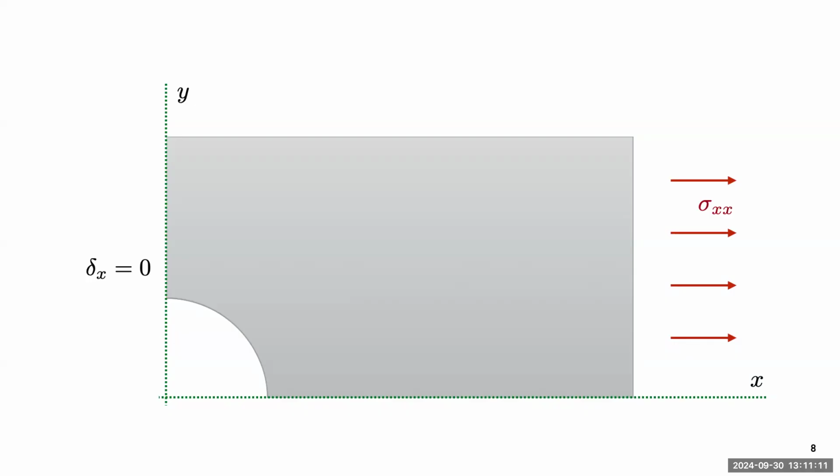And so then the normal direction to this symmetry plane, how do you find the normal? Sometimes people get confused. They say, well, this is the y direction, so y must be the normal. But normal means perpendicular. So perpendicular to this y plane here is the x direction. So that would be an x symmetry. A different way to think about that is, imagine the plate is 3D. So it has a certain thickness. So that plane, it would have a normal pointed in the x direction.